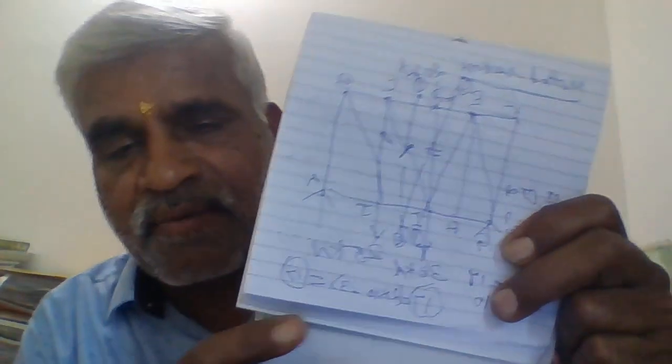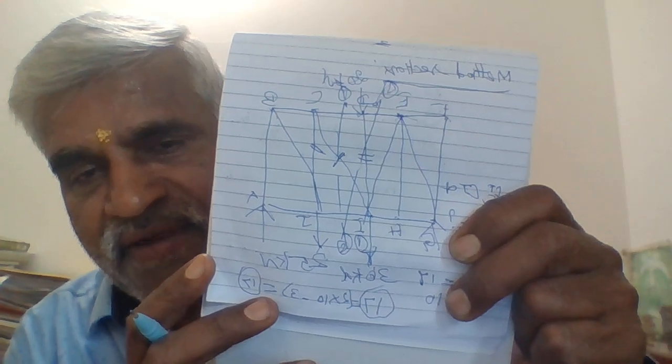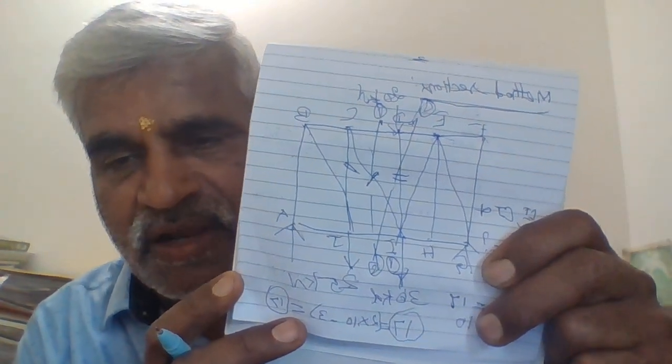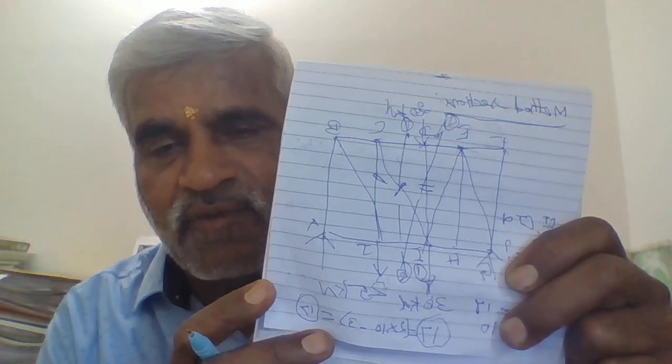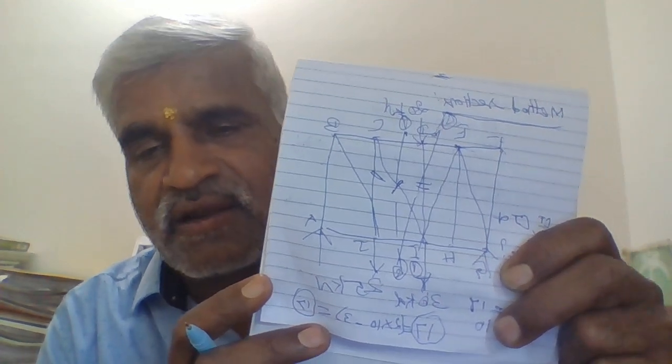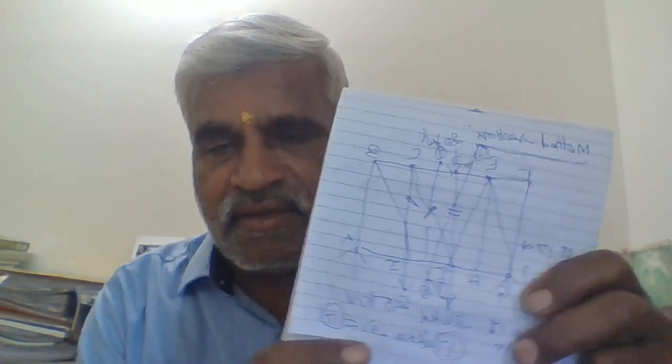You can have a maximum of two unknown member forces. So I cut the cutting plane like this, 1-1 and 2-2, so that you can apply vertical, horizontal and moment equilibrium. Two unknowns can be determined by taking sectional plane 1-1 at one time, and another time section 2-2. So we have to choose the corresponding members where we have to cut. That is very important in the method of section.